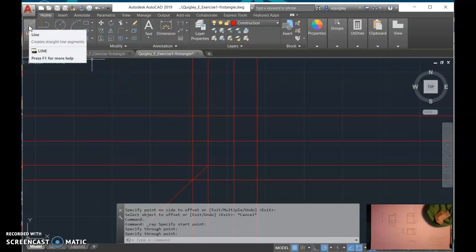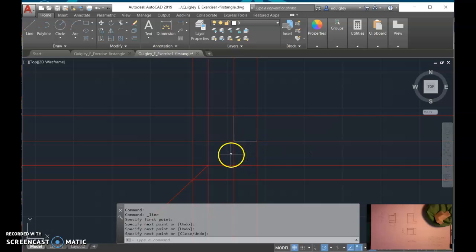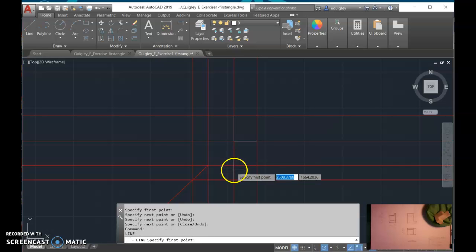So in the front view, let's draw some lines. Well, we don't want to draw lines until we're on the outline or layer 0. Now we'll draw some lines. So the left hand side of the object is the full height, and the base is the full width. So I can draw that much of the front view. The top view